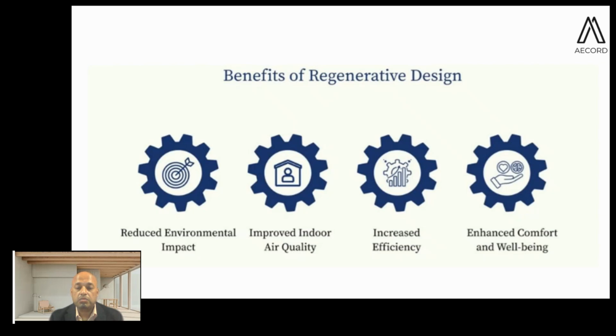So especially in commercial buildings, it has been analyzed and studied by a lot of universities abroad that poor thermal comfort or indoor air quality, or not having a view towards daylight from your office workspace, creates a lot of circadian issues in human beings, where it affects your night and day cycle, and it affects your sleep, and a lot of other ill effects on human health happen because you don't have good thermal comfort, good indoor air quality, and visual connection towards outside. So everything comes together as well-being aspects in the building.